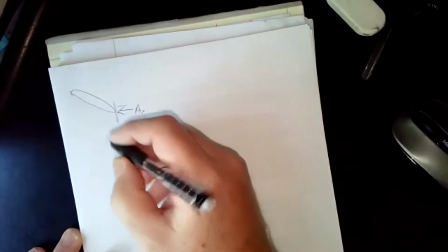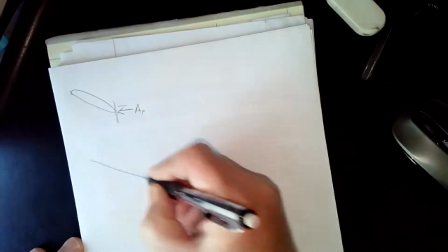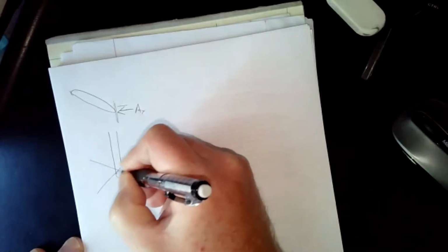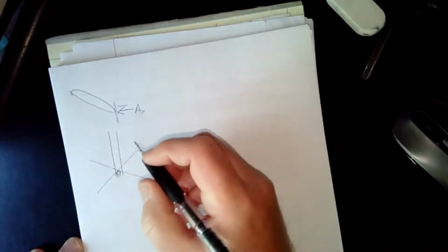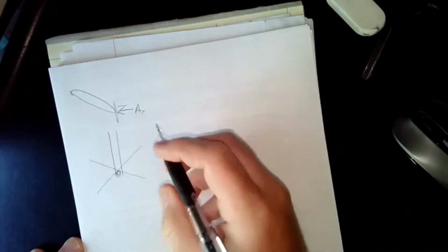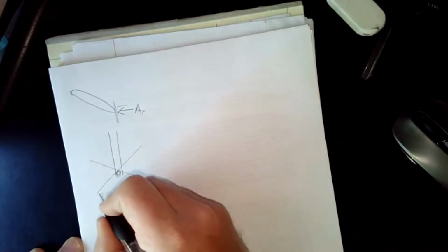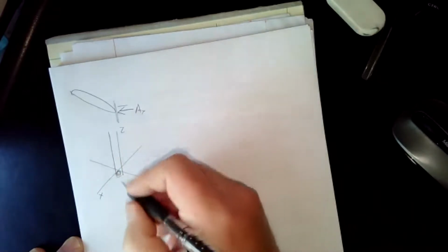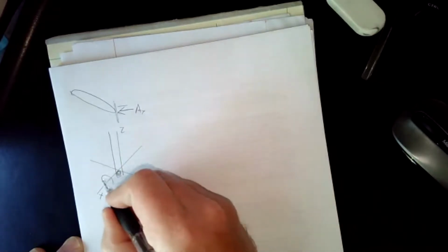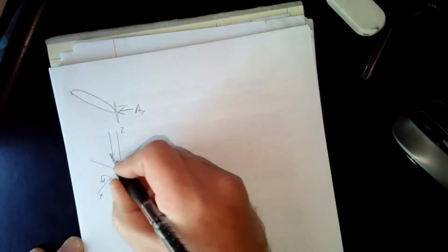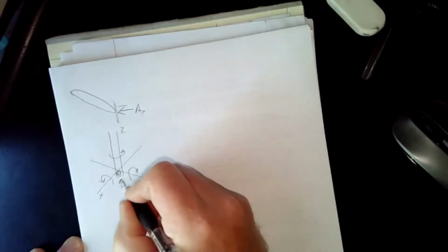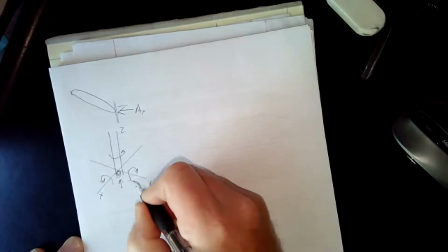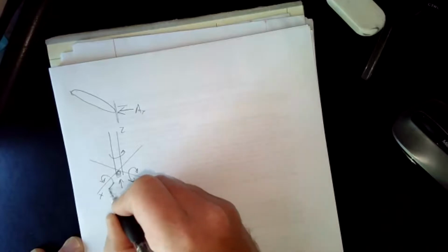So the most complicated would be in 3D, if you were to take, say, a pole like this, and let's say it's embedded in the ground, then in this case, if this is your X and then Y and then Z up here, then if it's embedded, you're going to have a moment about the X, a moment about the Y, a moment about the Z. You're going to have a reaction force in the Z, a reaction force in the Y, and a reaction force in the X.